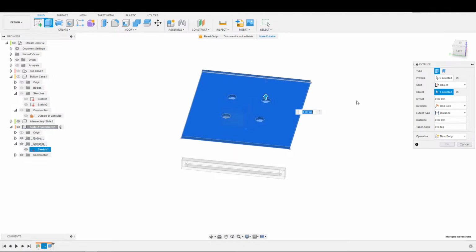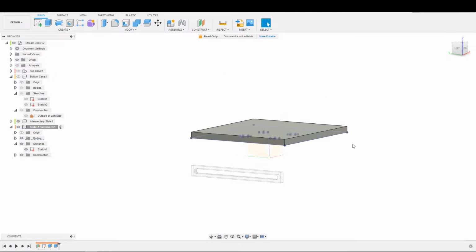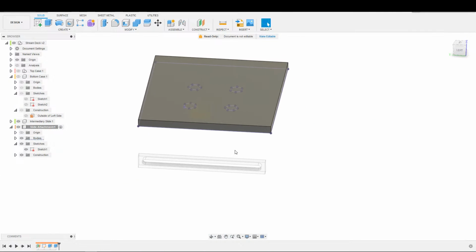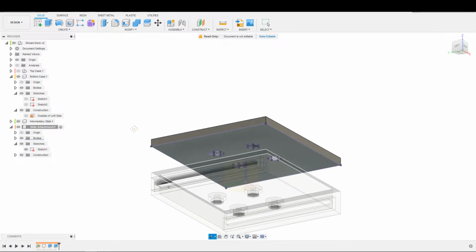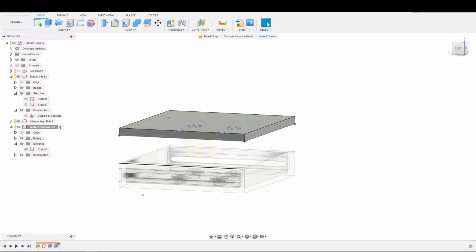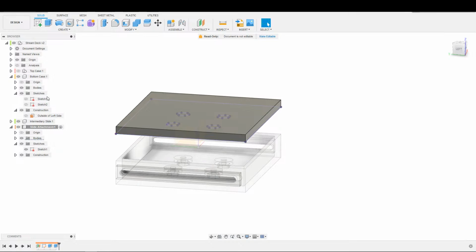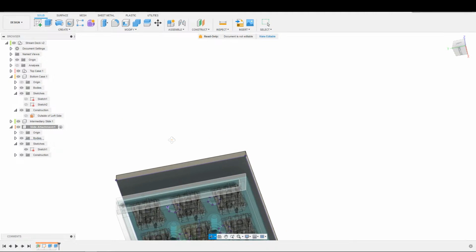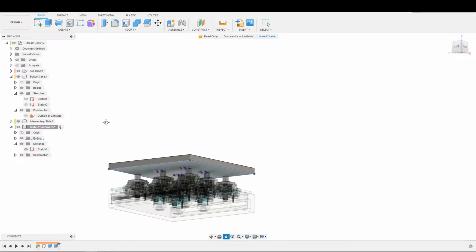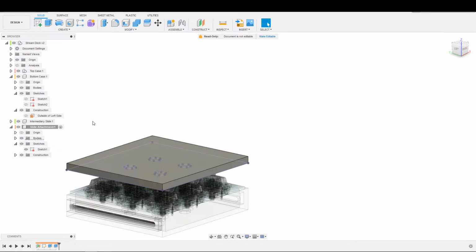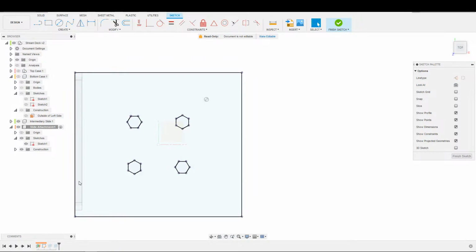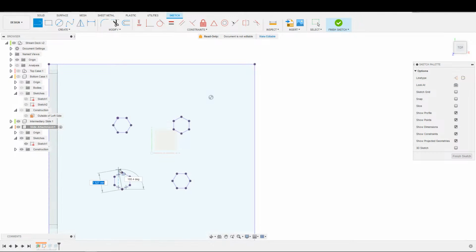From object, 2 millimeters. And now I've got some captured nuts in the bottom here, is what just happened there. In this case, instead of the bottom case using its captured nuts to attach to the top case, we'll actually just run an extra long bolt all the way through all 3 of them and use the captured nuts on this roller plate is the idea here. That does mean, however, that I do have to throw these M3 bolts in because that did not get transferred over because we only took A.